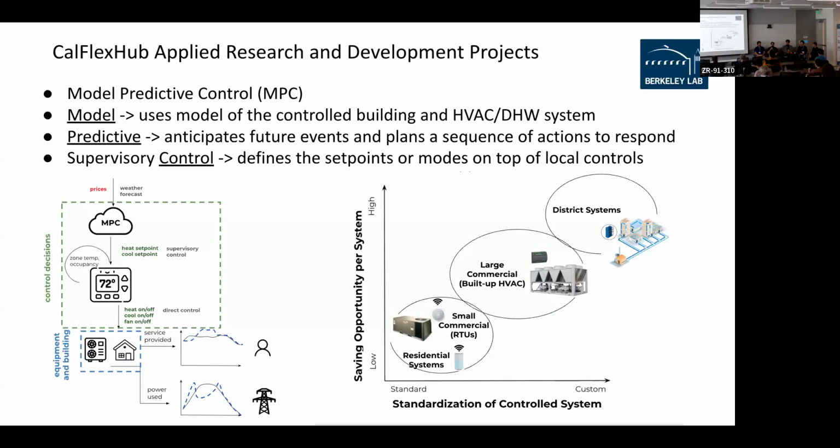and each zone is a simple gray box model with an RC network, because we realized that more complex models tend to be a little more accurate, but the data you use to calibrate them has to be very good. So there is a trade-off between how complex your model is and how reliable it is. In our case, we do recursive training of the model once every week. Then we just use the latest version of the model so that any changes in the control logic and the seasonality are accounted for in the model. And it's been behaving pretty well from that point of view.